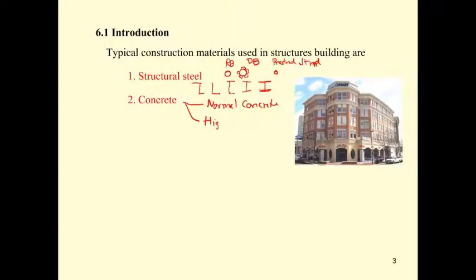And for some high-rise buildings or special structures, we can use high-strength concrete. Usually it has an ultimate stress f'c larger than 400 ksc, and nowadays it's changed to 600 ksc. It is up to the standard of each country. In Thailand, you can order ready-mix concrete with strength up to 800 ksc, kilograms per square centimeter, from SCG or TPI or from other companies.